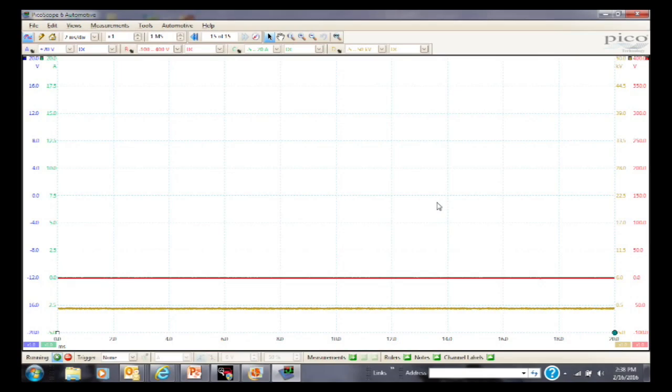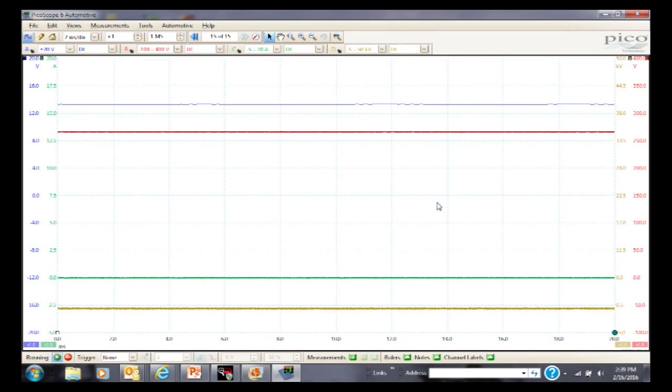Before we do that, let's do a key on engine stop. Watch the 2 lines, the red and the blue. Blue is supply voltage, channel A. Channel B, there we go, they both pop up. If you look at the exact measurements, the right versus the left, we've got about 12, 13 volts, so that's good. Now let's go ahead and crank it up and we'll watch the other patterns.